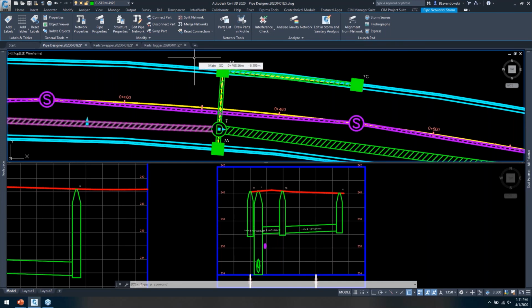If we look at Pipe Designer, where we're designing the pipe runs, you wouldn't necessarily have that stuff in a separate network. Perhaps there are reasons if it's, say, an existing structure that you're tying into, but if it's existing, you're not really changing that one, right? I know people have different workflows there. So with Pipe Designer, no, because we can't read and edit that stuff if it's in separate networks.